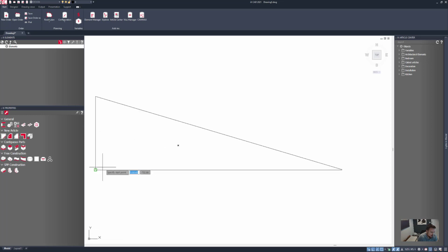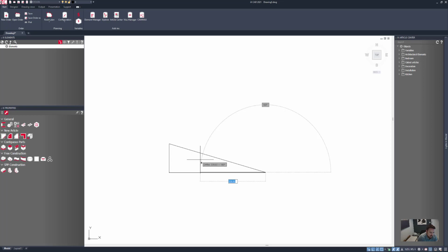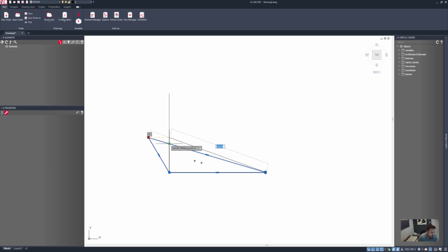So I've drawn out, up 1 millimeter, and then I know that I want my angle to come back a certain distance. You can see with dynamic input ticked down at the bottom, I can tab between and type in my angle, which is going to be 164 degrees. That gives me a line that's coming off in this direction. I'll click anywhere and then come back to my endpoint by pressing C, enter for close. Then if I draw another polyline from my start point straight up, I can snap back to this intersecting point, and that's going to give me my line work.